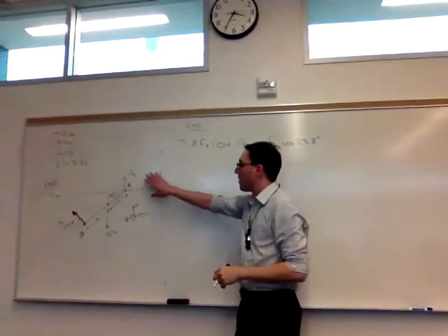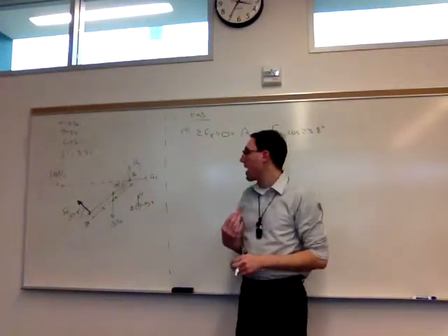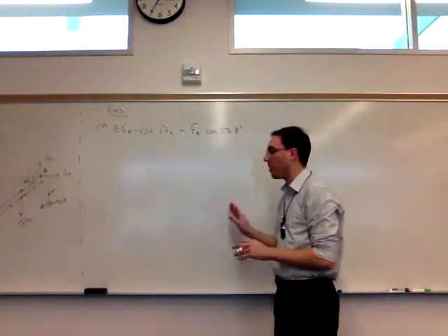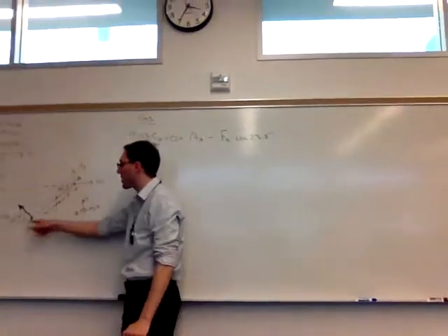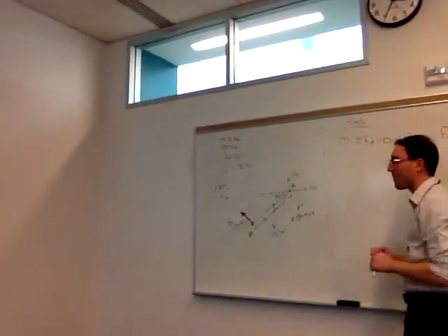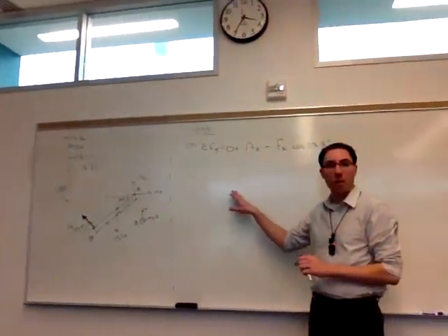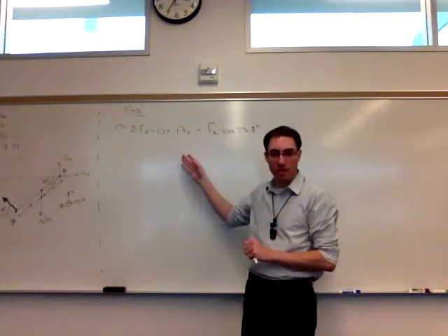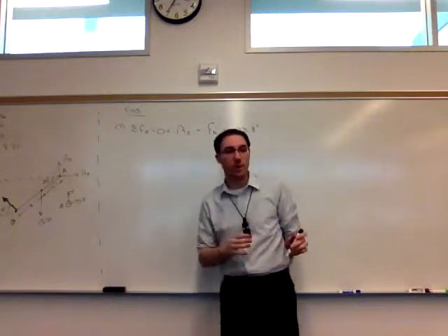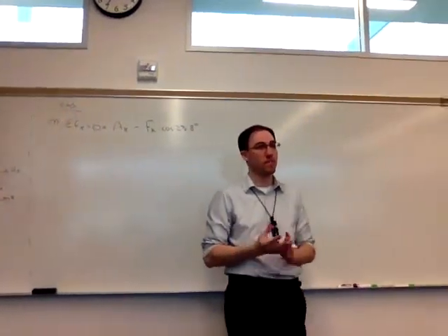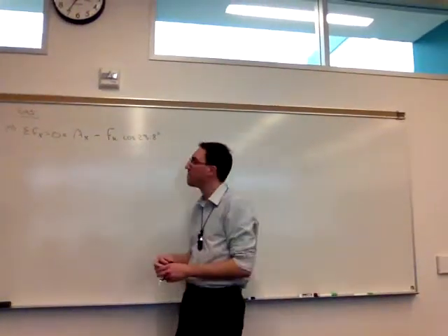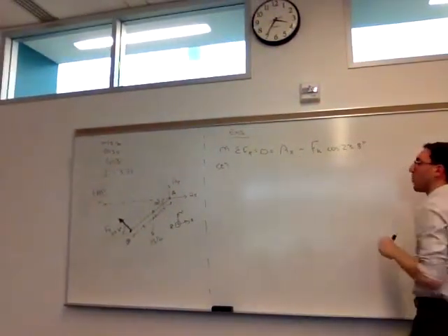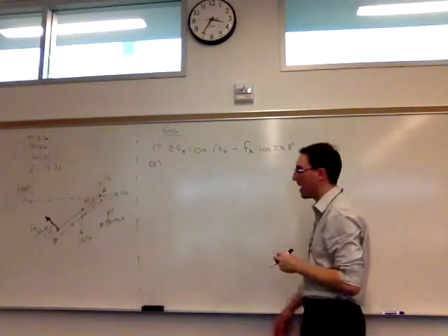And to reiterate, the pin at A, I'm making the assumption that Ax is positive, or is to the right, and Ay is up. That could go in either direction. Down here at the spring at B, I'm making the assumption that Fk is in tension, and that will reflect how, because it's a spring, we're probably going to need a Hooke's law equation, as we'll see. That means we have to use the Hooke's law under the assumption that tension is positive. All right, so that's our first equation. We have 2 unknowns, 1 equation, so I'll just put it aside for right now.